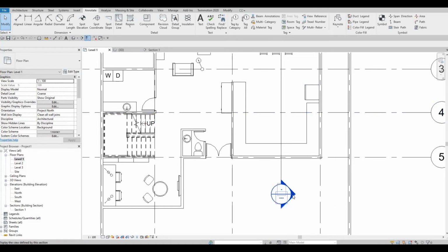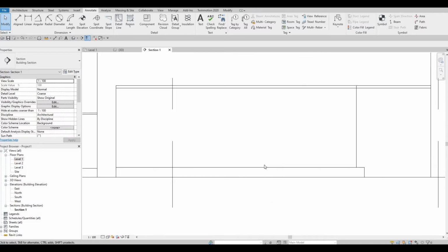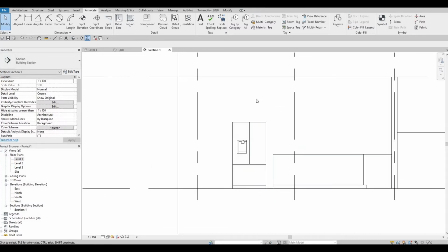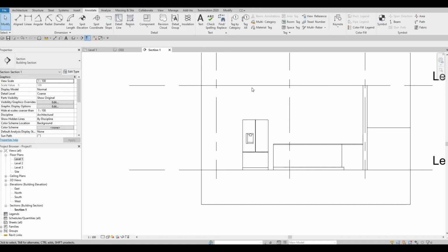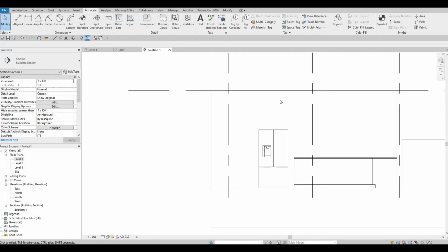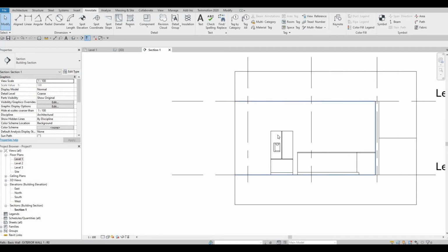Now I'm gonna go to my section, and then here I'm gonna create its case. So usually I'm gonna create a case all the way at the top, negative 200 for the thickness of the floor. So we need to, it's basically 2800 because we set it up at 3000, right? So minus 200 is 2800. That's for the floor because the floor will be sitting around here.